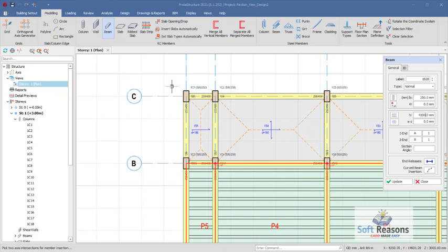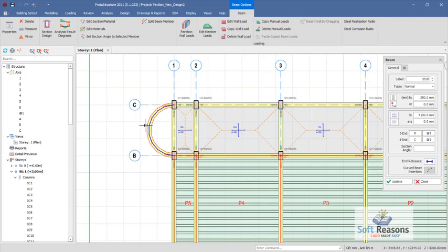So this beam is going to be anchored from the foundations. So how do I get this 4500? It is gotten by adding the foundation depth and the story height. I'll be using the curve beam insertion option, this one. So pick the first point, pick the second point, move your hand this way to get a radius. You can do shift F2 right there to key in the desired radius, which I want to be 1500. I hit enter to have my curve beam placed just like this.